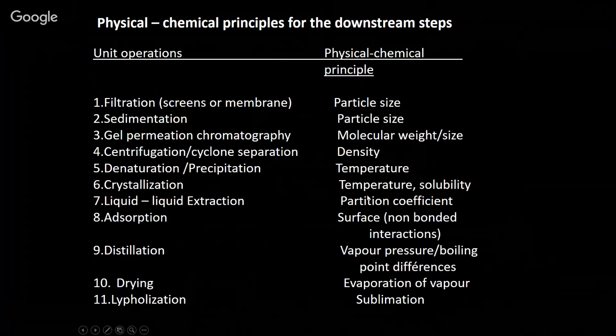Okay. So many downstream processes: filtration, removing a solid from a slurry. That's called filtration. Different types of filtration. Sedimentation, again, you allow the solids to settle down. So these two techniques are based on the size of the particle. Larger particles settle down nicely, smaller particles don't settle as much, and so on. So I have filters of different pore size, different diameters of pores. When you have larger particles, they get stopped, smaller particles pass through. So they are based on the principle of size of the particle.